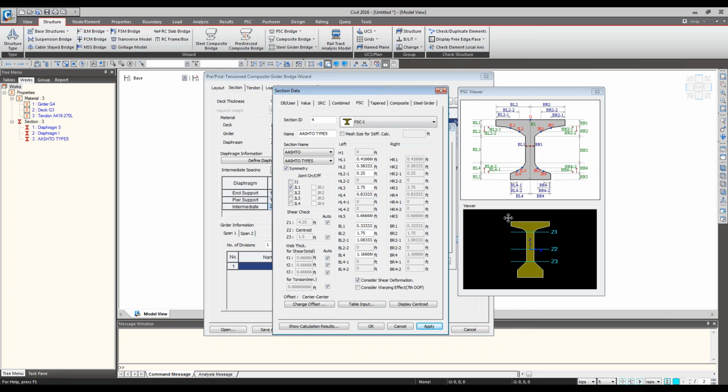If your girder has to be elongated at the flange or at the web portion, whatever the case may be, for the splice girder you will have to lengthen the girder, or above the pier for the concrete pour, if the bottom flange needs to be thicker, you can freely modify that any way you need. So from 0.6 to 0.5, I could increase my flange thickness like this. This way you can freely manipulate the section based on the database.